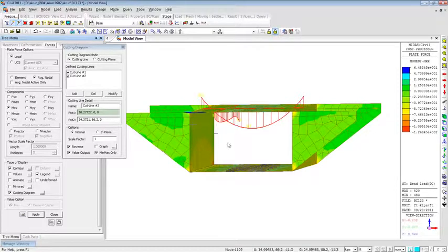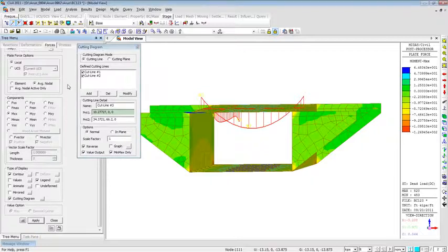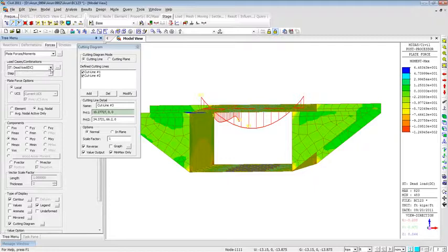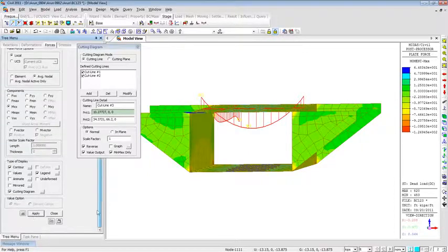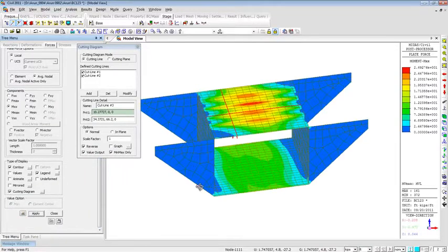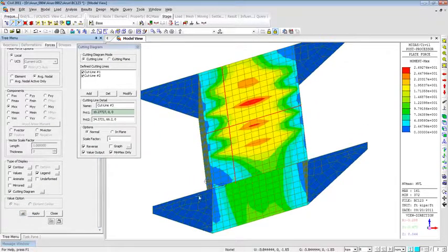And having done this, let me show you some live load results as well. So for the plate elements, you can choose, let's say, MV max, which means maximum positive bending moment envelope, and click apply, and this is what the program generated. So this is the live load envelope contour plot, and I can choose any element and generate the loading pattern for that same. So if I'm curious to know what loading pattern causes maximum bending moment at this